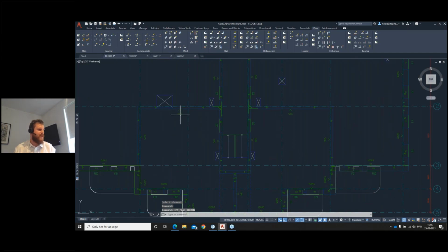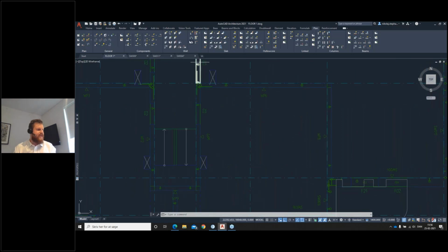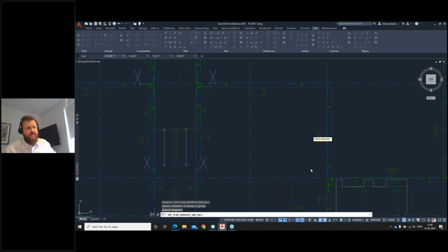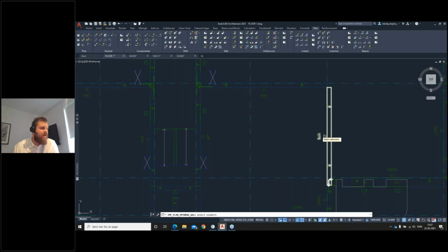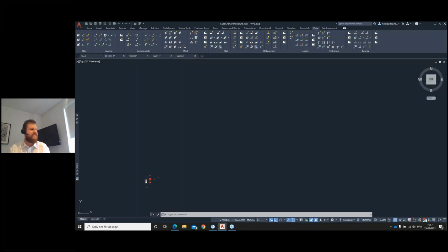If, for example, we have a wall panel, let's take this wall panel 8, just to show you something different. The sandwich panels are typically the most complicated ones to do, of course, to have all the drawings. There are so many details, insulation, and so on. The solid wall panels are a little bit more simple, and often you can get away with just one drawing on those. You don't need all the extra. Here it's maybe more okay to fit it into one piece of paper.